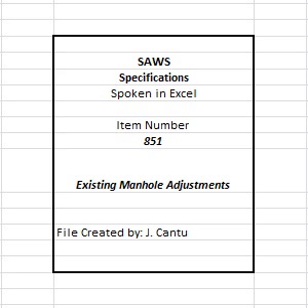851.4 Materials. 1. All material and construction work shall be in accordance with current Texas Commission on Environmental Quality, TCEQ, rules to include Design Criteria for Sewage Systems, 30 TCEQ 217, and Edwards Aquifer Recharge Zone, 30 TCEQ 213, or any revision thereto as applicable. 2.